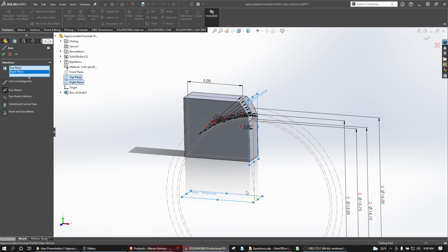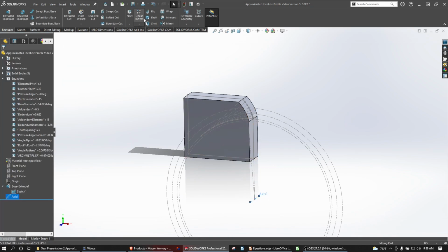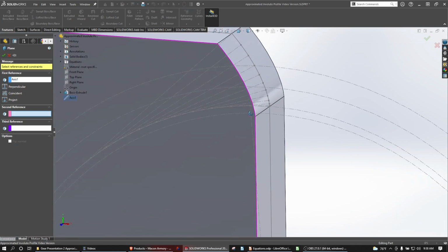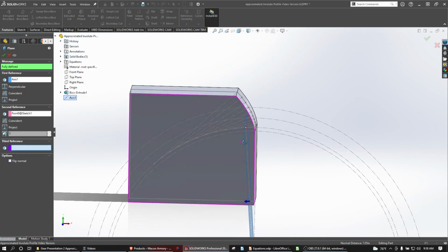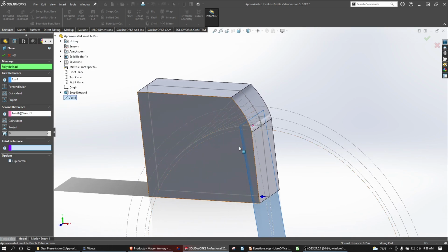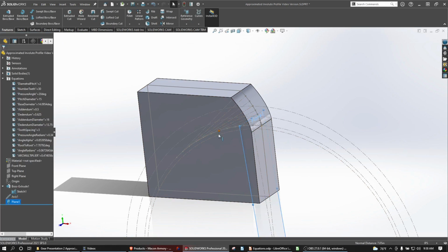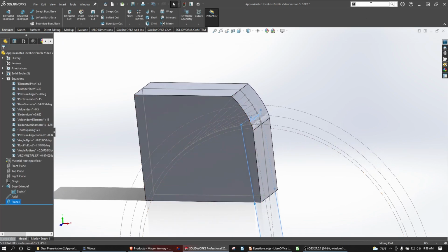And so where these planes intersect, the axis is created, and where the axis is created is actually going to be the center that the gear rotates around, because it falls right on our sketch origin. So I create an axis, I'll create a plane on that axis, and then I can specify a point on the midline, and now this plane becomes like a 3D midpoint reference to our tooth. So I'd like to split this tooth.